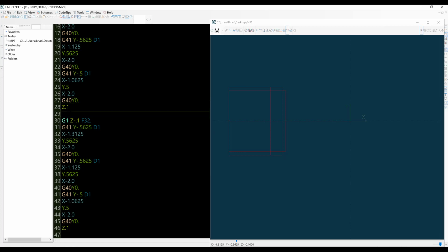But it won't be a bad idea to change here and go to G00, and then go to x 0, y 2.0. My mistake. So we're going up in space, so we have to move around a little bit, right around there.